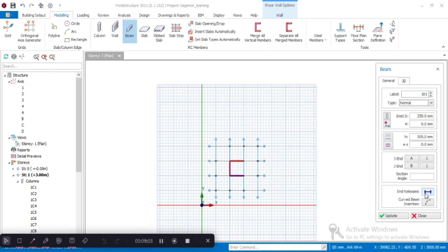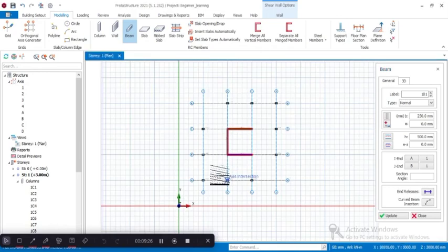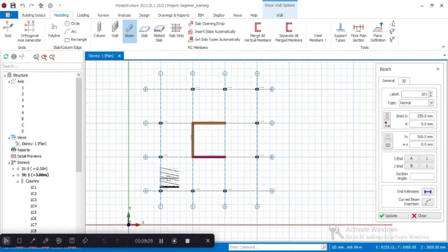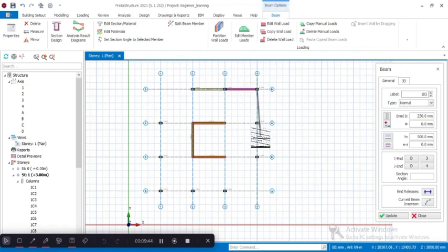In the beam properties, use the default values 250 and h, the height, 500. Then to create a beam, click on the intersection of axis for the start and the end of the beam. Notice that you can continue to create the beams from the previous beam continuously. So let's see what that's about. We are following their guide here. According to what is on it, we can put our beam singularly. If you extend it, it will break automatically. That is how it's done here.